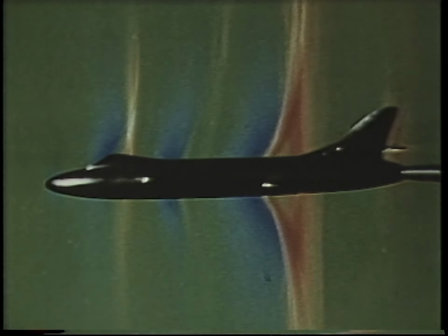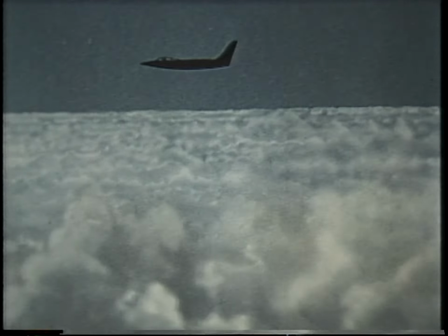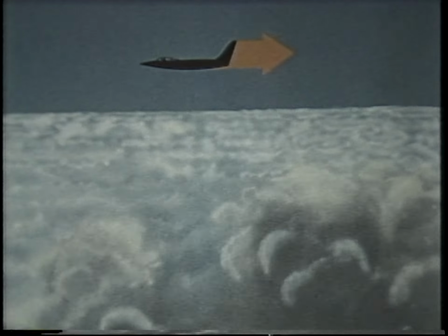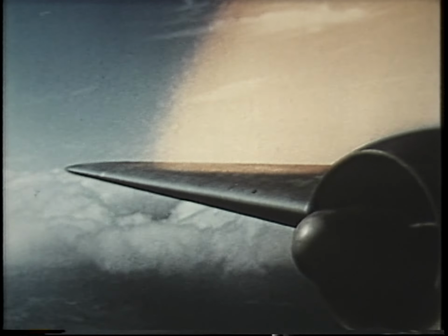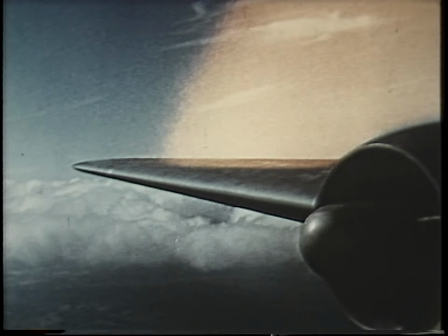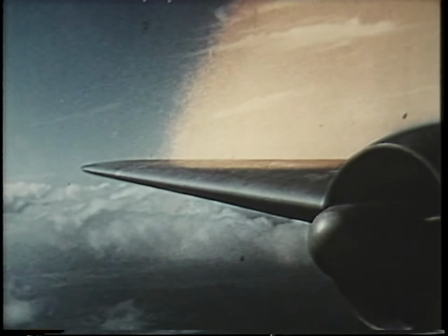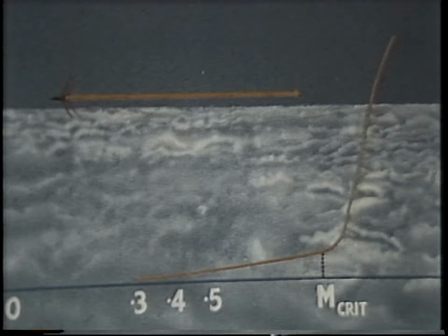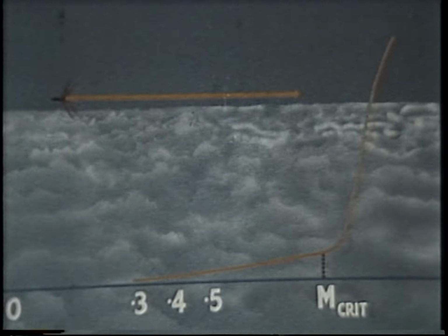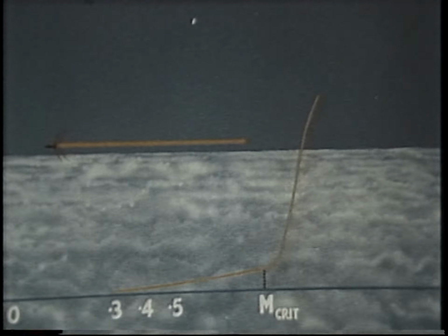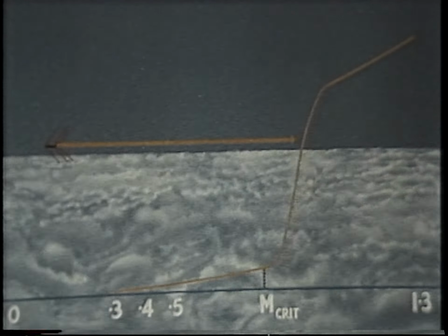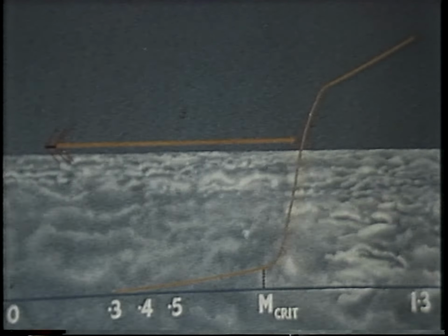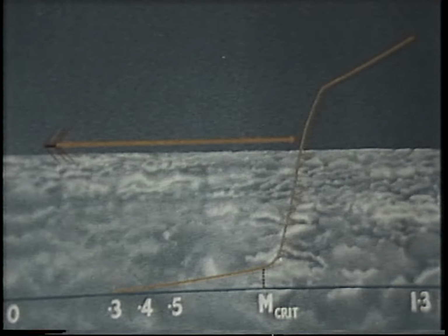The most striking effect of shock waves is a sudden, very sharp increase in the aircraft's drag. This is because the shock wave heats up the air and compresses it. And this absorbs a lot of extra energy, which has to be continuously supplied by the engines. The rate at which the drag increases is itself highest somewhere around Mach 1, although the actual drag goes on growing all the time. This sudden increase in drag above the critical Mach number is what used to be meant by the sound barrier.